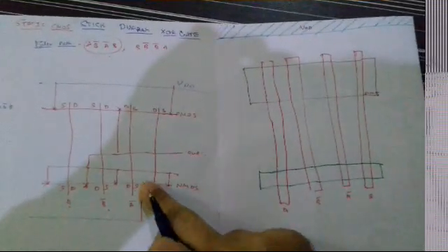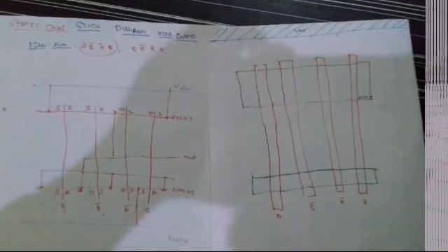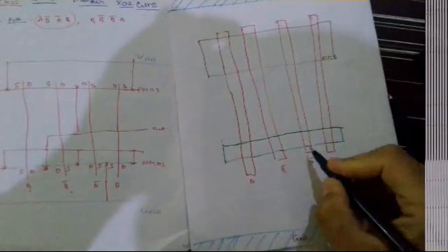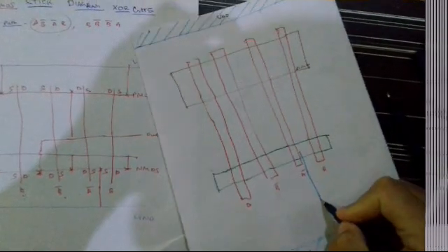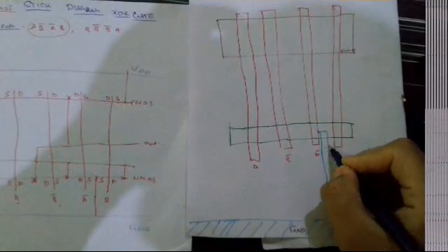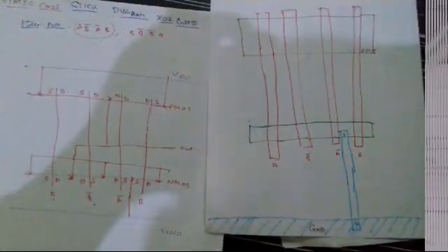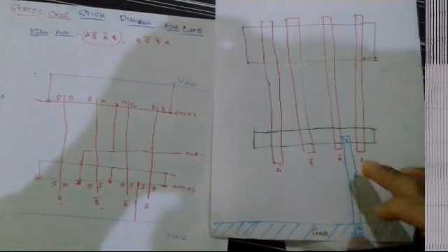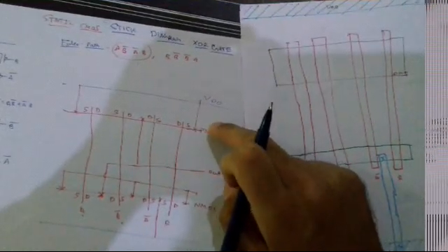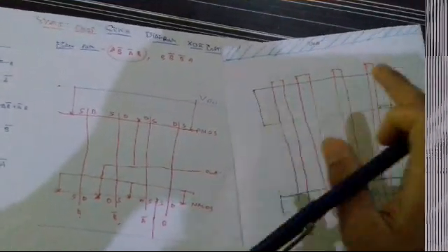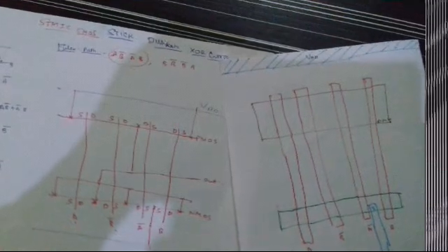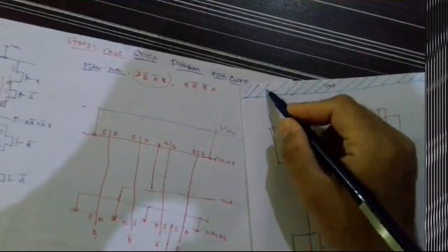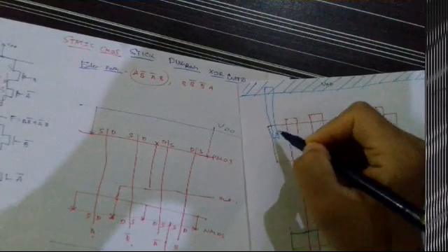Now we see that the sources of these 2 terminals are connected to the ground terminal. So for that I will take the metal layer which is of blue color and join it. After joining the metal layer with the ground, I will see that this is connected with the VDD and this also is connected with the VDD. So these 2 sources must be connected with the VDD terminal as shown. This is for making the contact.